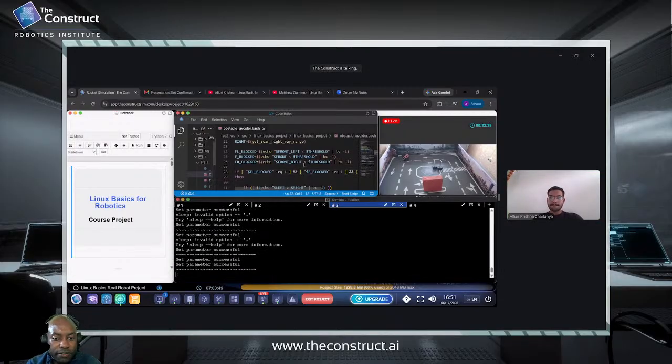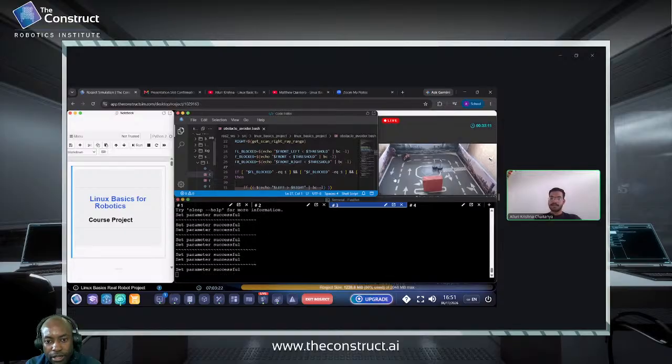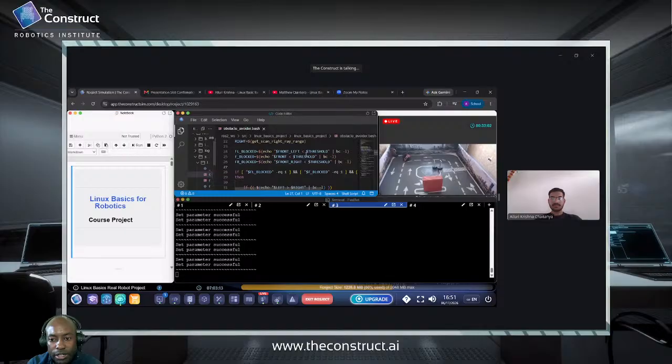So what I would say is you would have to check these, and get a full understanding of where it might be falling short. However, the thing I want to make clear is that 0.7, even though I say that's too big, would have worked anyway if the logic there was good. It would just excessively restrict the possibilities of the robot to move around, but the logic would still work. It would still be able to find places at a distance of greater than 0.7 from obstacles. So you have those two things to make amendments to.